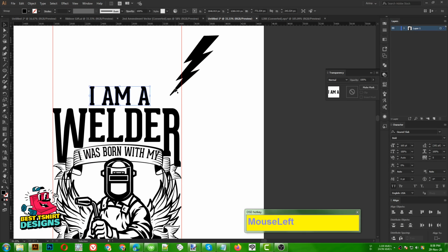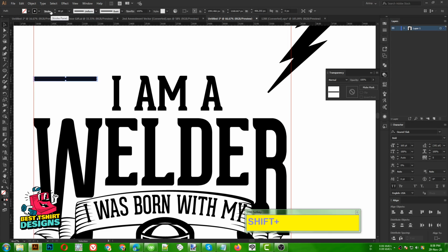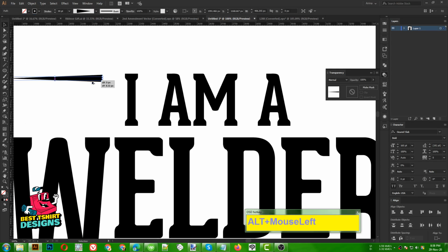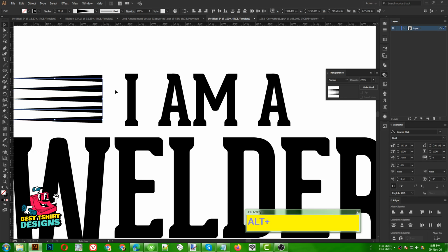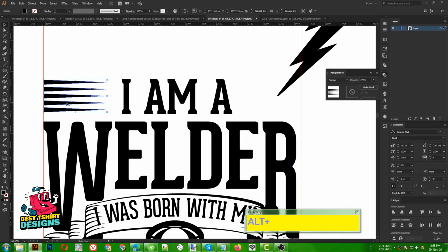So I wanted to create something like, okay, let's create the same effect of our American flag on. Just create a stroke like this, then press Shift X to make it a stroke, make it something bigger, then select this option, that is good. Now I am going to make a copy here, just like this, then press Ctrl D 2-3 times, then select it, align them, go to object and expand appearance to make it a fill color, then rotate like this, make them a group, make a copy here, just like this.